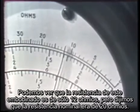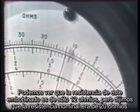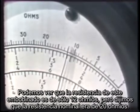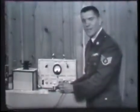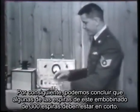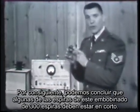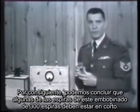We'll see that the resistance of this winding is only 12 ohms. But we've already pointed out the normal resistance of the 300 turn winding is 20 ohms. Thus, we can conclude that some of the windings or turns of this 300 turn winding must be shorted.